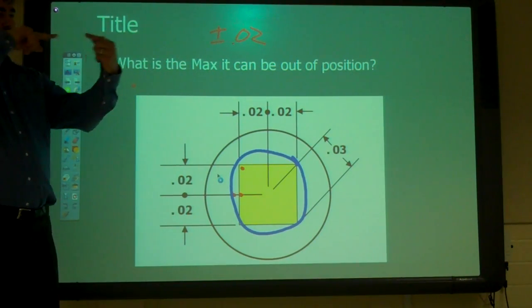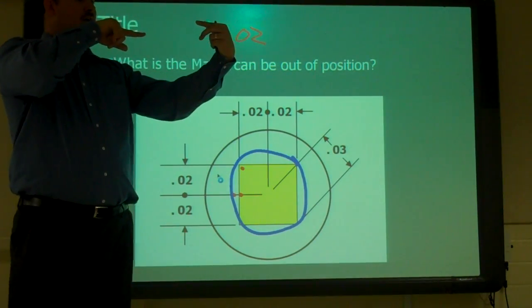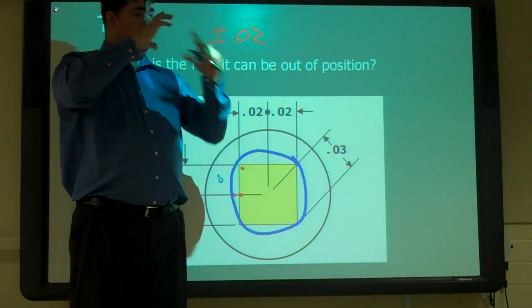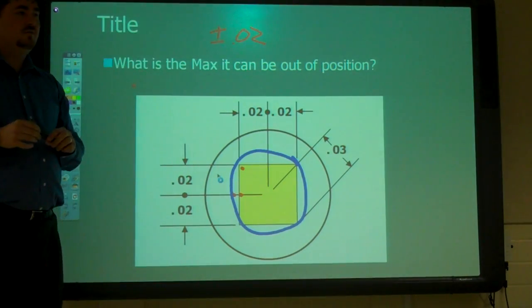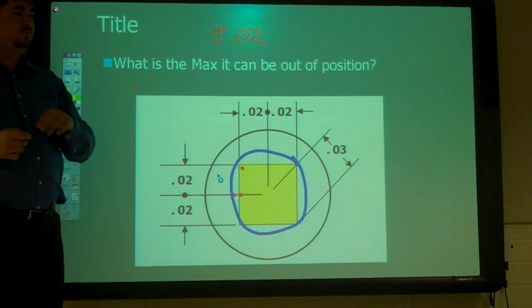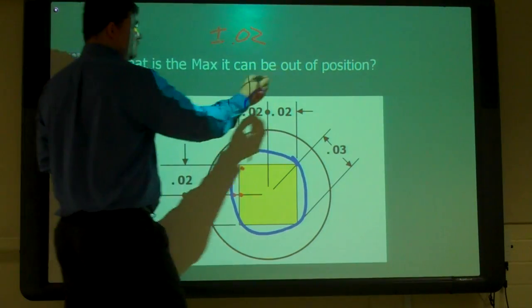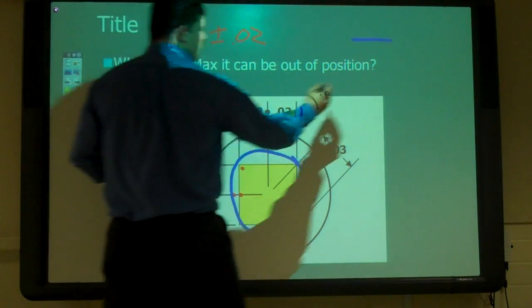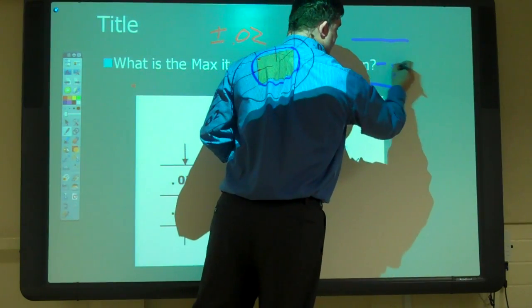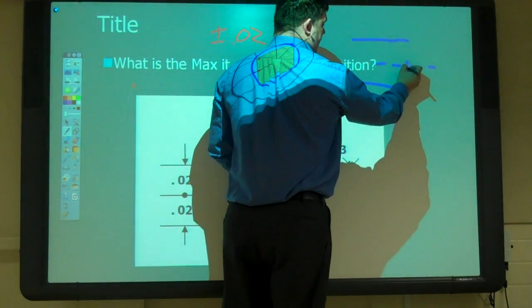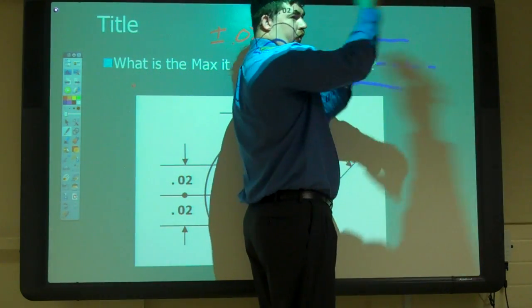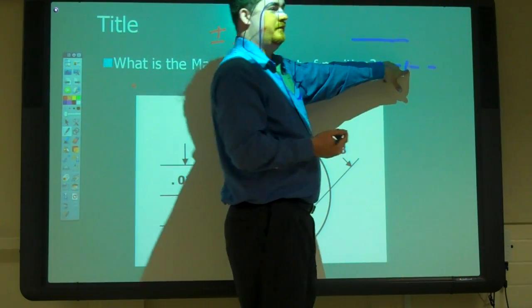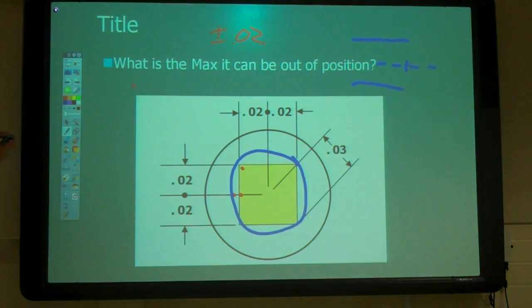No. But you're still talking about the center of that camshaft needing to be lined up. So if you're allowed to be outside that center more, then it's going to wobble even worse. You'd want to have the same GD&T, which affects the shape. If you have that shaft here, there's your center line, and you want that to be evenly spaced up and down, or all the way around it, right? Because if you made it so you can go further here, then it's going to be further away from the center and it's going to wobble. So that's not really what we want.